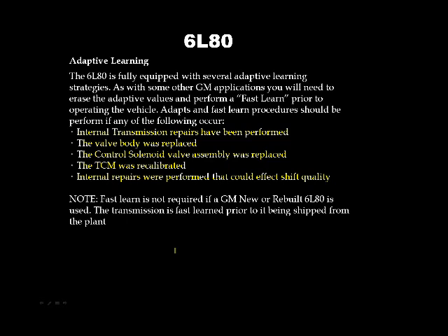So let's say you bought a reman transmission that was not a GM. If it's not a GM, you're going to have to do a fast learn. The GMs are all fast learned at the plant.